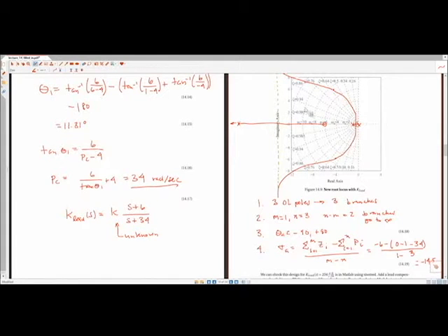The asymptote location is more for completing the root locus plot, so that all of you understand what happened to it. In terms of design, the most useful aspect is actually placing a pole directly where you want it, which was the angle rule that we used on Wednesday. Calculating sigma A to figure out where the asymptote is, is not all that important once you do the design, because you care about where the dominant poles are placed, not where the asymptote is if we crank up the gain to infinity. It's just to show everyone what it looks like.